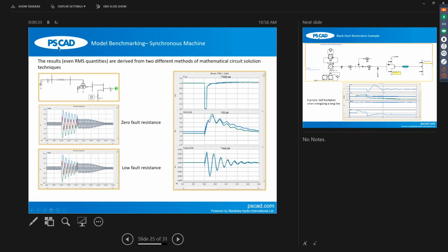The DC offset has not decayed sufficiently for the current to cross the zero crossing, right? So even though you tell the PSCAD or EMT program to remove the fault, in EMT programs, the currents are interrupted always at a zero crossing, right? So in PSCAD, the current will not be interrupted after 0.1 seconds. It may wait for the current zero, right?